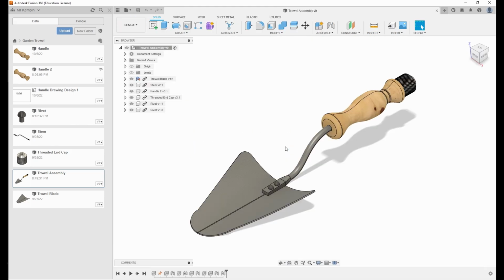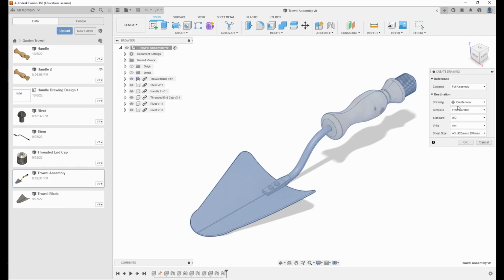We don't need this. I'm going to show you how you can go design, drawing, and from design. And when it says template, I'm going to teach you how to do a smart template. And you can see I've done some tests here. So the smart template test will take everything on, and external components, that refers to any linked components I've got here. So because they've come from linked from other individual parts, we want to include them, otherwise they won't be dragged through. You don't want drawings for any parts you've got linked from other designs. Say you're doing a larger project and you're reusing components, perhaps off-the-shelf components, you can leave that unselected. But I'm going to do this for this.